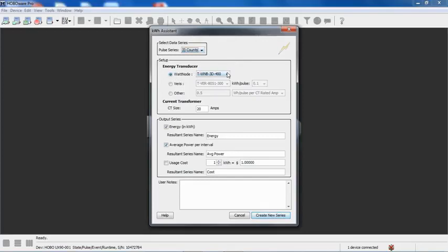I know it was a WattNode, and again, you have to use some diligence. You have to write down the model number you're using and the CT sizes, because if you don't put the right value in here, your data will be incorrect. So I know this was a WNA3D240 that I was using, which is the Delta version of the 240 volt WattNode, which does not require a neutral. And I know I had 50 amp CTs on here. Again, this is what they call a split phase circuit, so two hot leads and a neutral, but I used the WattNode that doesn't require the neutral.